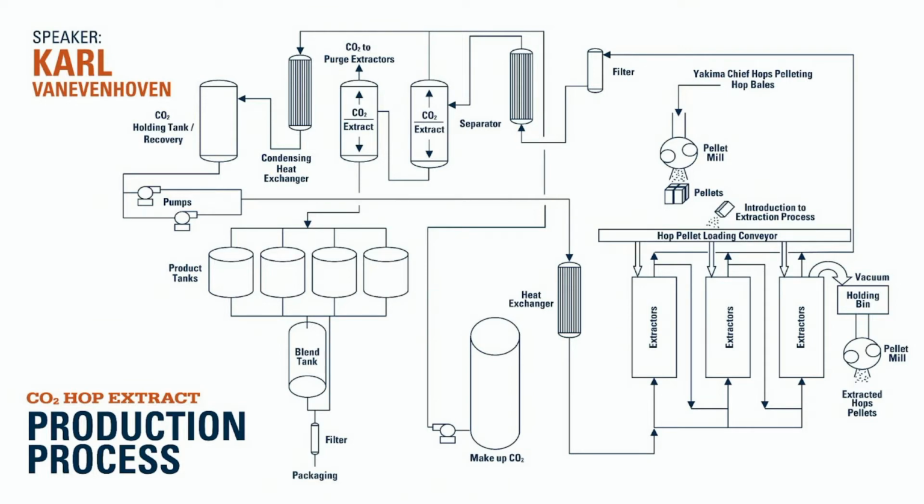I'm so glad we have you technical guys here today to explain all this for us. How much of the CO2 do we recapture? The standard process that you see there, we recapture 98%. But under the sustainability side of the company with our corporate social responsibility, we added a CO2 recovery system. So we're recovering about 65% of that remaining 2% that we were losing. So we're over 99% now. And we're always looking at ways to recapture that last bit, but there's some parts of the process we just can't recover that CO2.